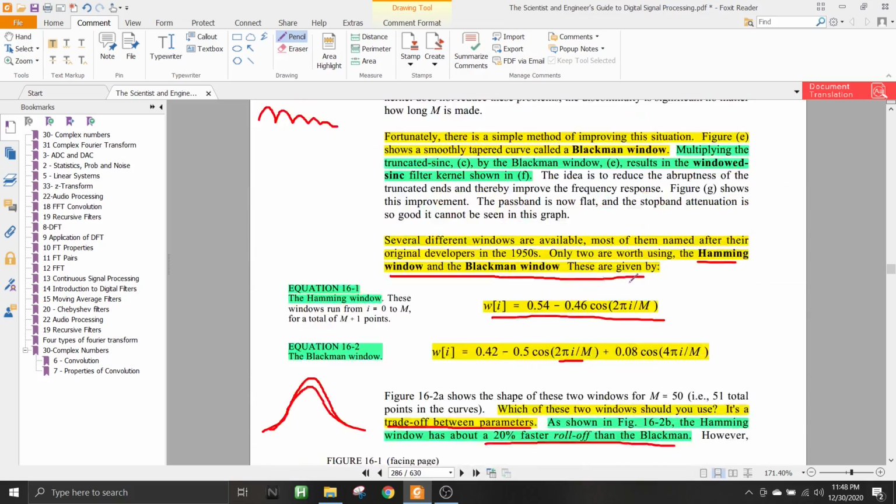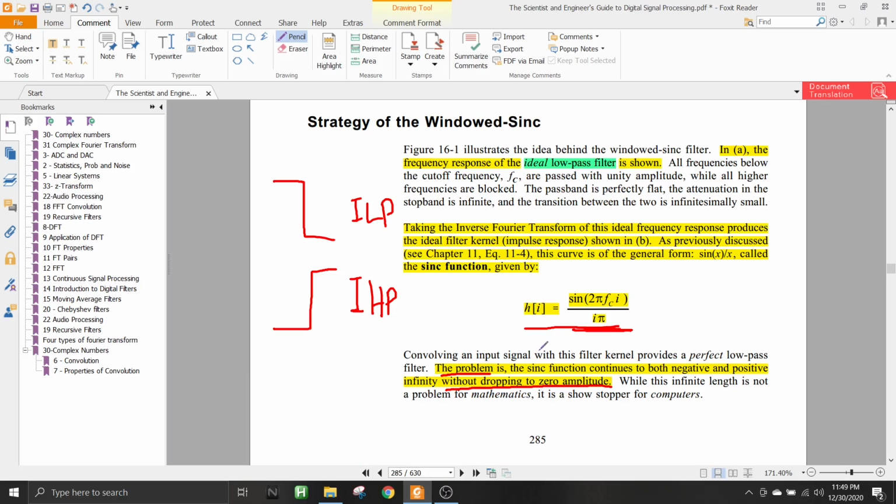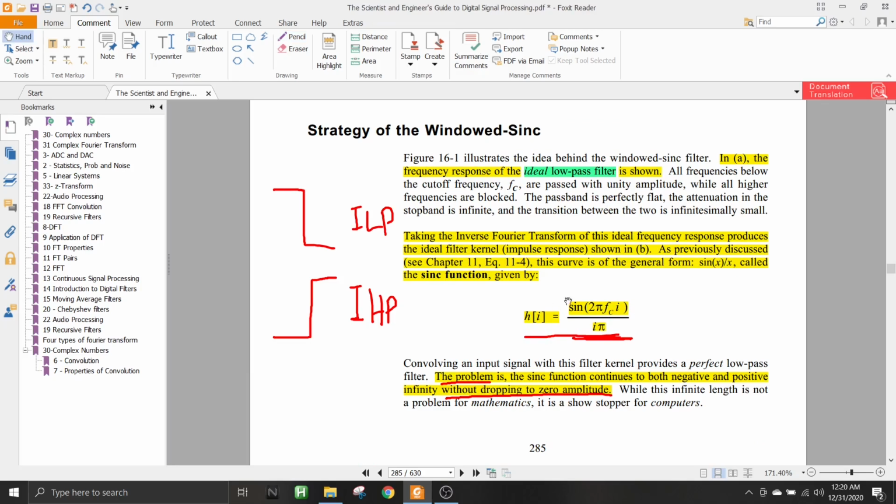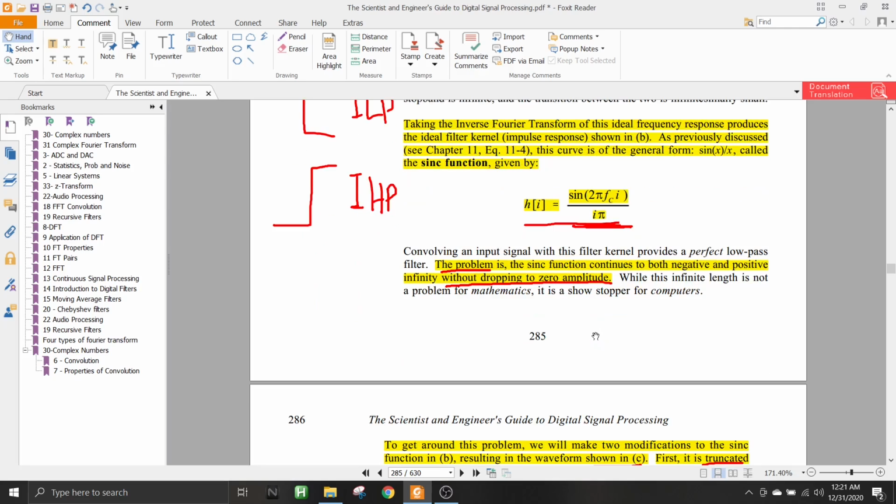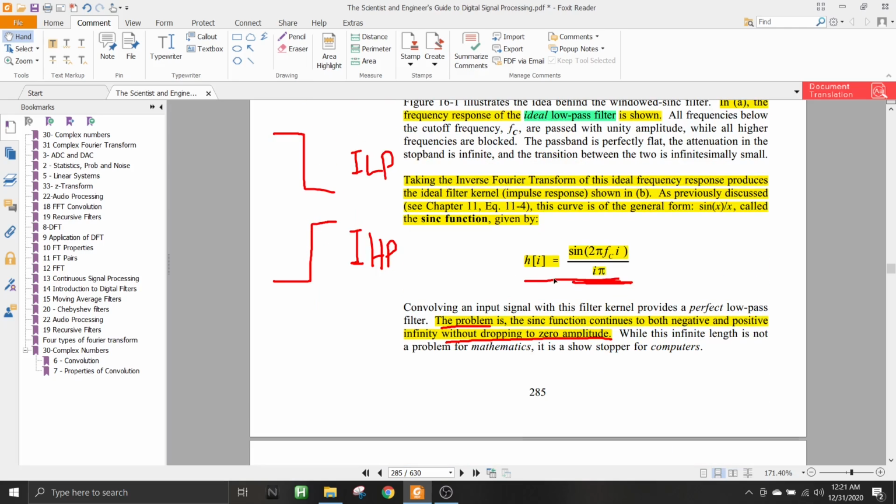But now we are not taking this one. It should be noted that this equation here was the equation for the ideal window sinc function. We are not using this actual ideal version. We are truncating it, multiplying with the Blackman window, picking a particular cutoff frequency, and taking a particular filter length M. After doing all of that, we can get the compressed version, a single equation that will represent all of these things that we just did.